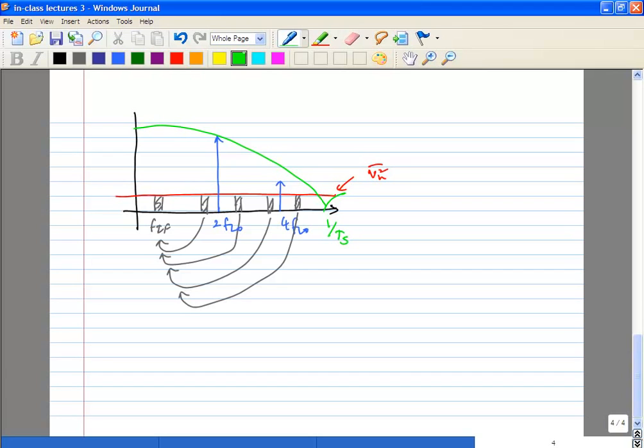So what happens when you increase the size of the transistor? TS drops, which means 1 over TS, the sampling bandwidth, increases. So you actually add in more noise, but the input referred noise floor actually goes down. VN actually goes down. So overall it ends up compensating, so that the output noise due to the switches is independent of the switch width.